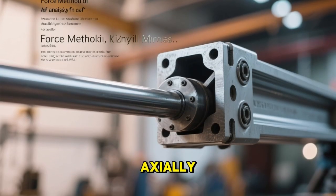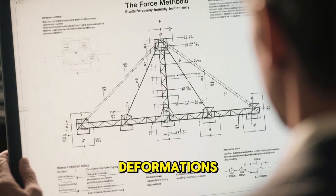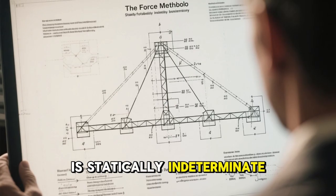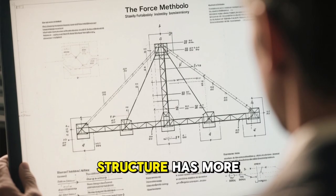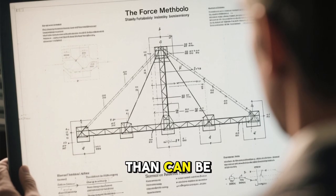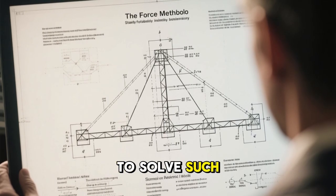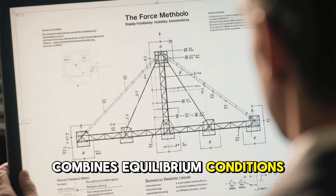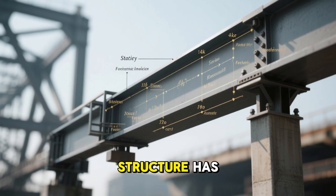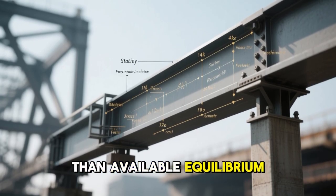The force method of analysis for axially loaded members. The force method, also called the method of consistent deformations, is a structural analysis technique used when a structure is statically indeterminate. A statically indeterminate structure has more unknown forces, support reactions or internal member forces, than can be found using only the equations of static equilibrium. To solve such problems, the force method combines equilibrium conditions with compatibility of deformations. A statically indeterminate structure has more unknown reactions or internal forces than available equilibrium equations.